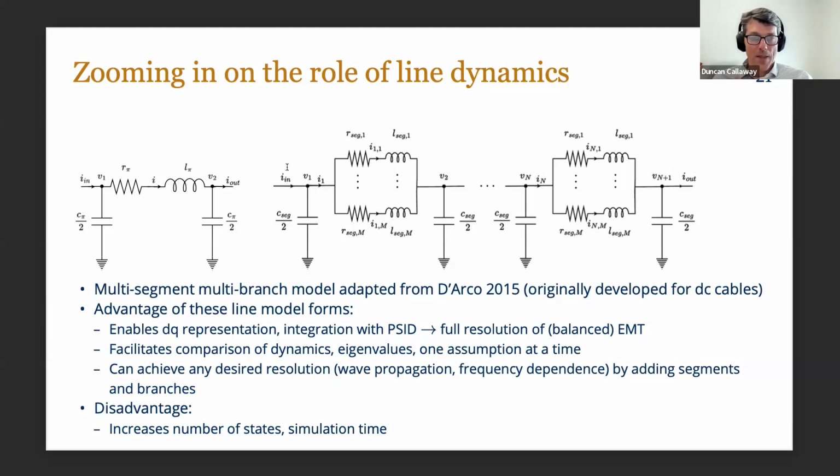From where my mouse is, about a third of the way from the left of the slide, all the way over, that's one model, where the idea is that you could discretize the model in space so that you've got capacitances along the whole length of the transmission line and inductances and resistances sitting in between each pair of capacitors.